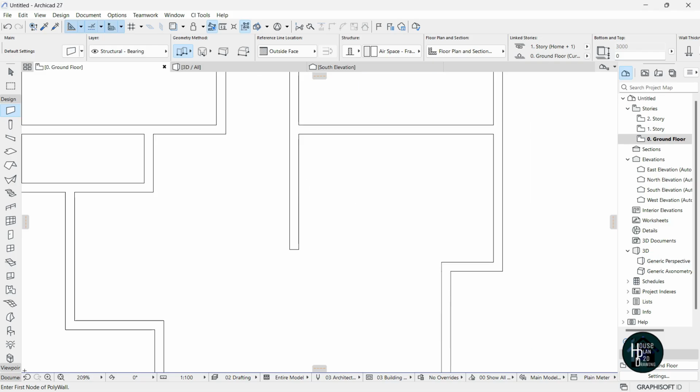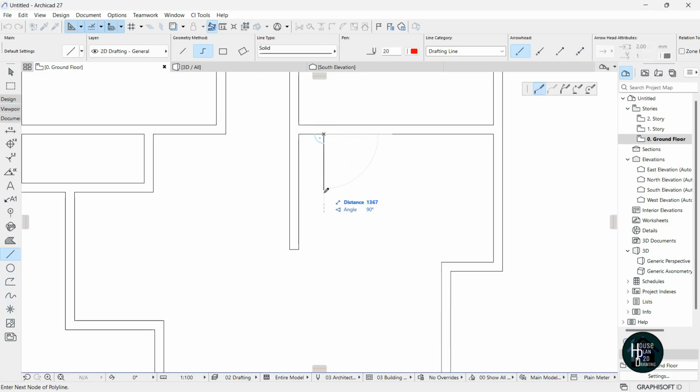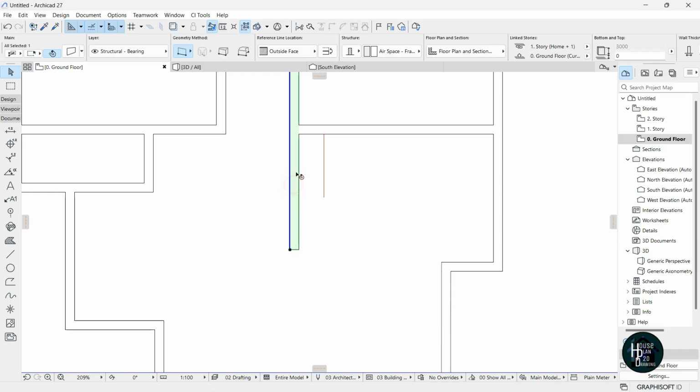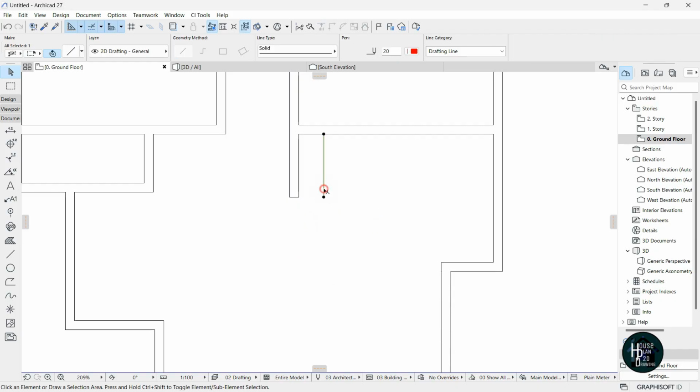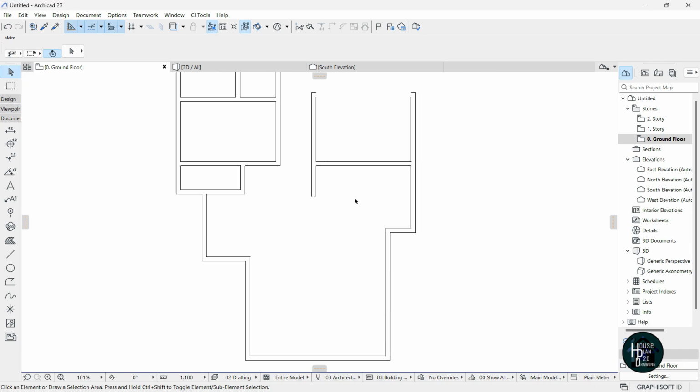For this side now, once it's come to the document tab, click on the line tool, click this, stretch it down and give a distance of 1551, then click enter on your keyboard. Click this wall here, click on this node, stretch it back like this, hold down shift on your keyboard and click this side. All right, click on this line, delete it.